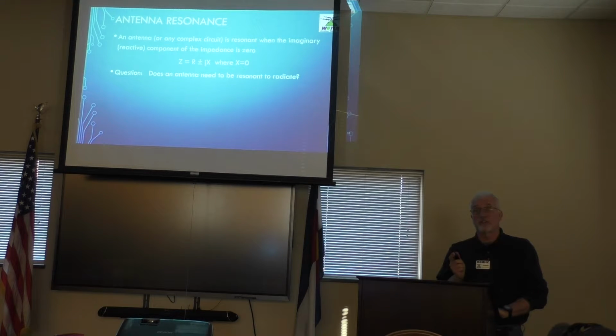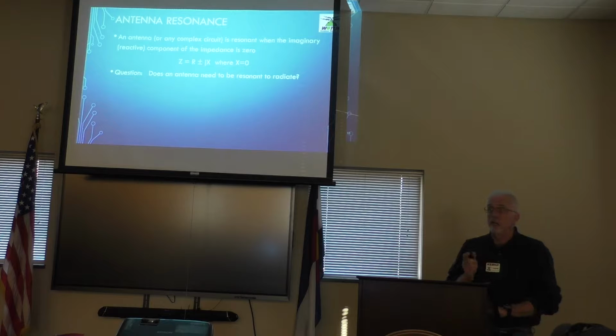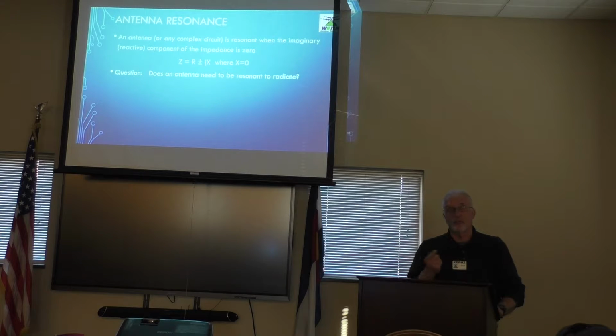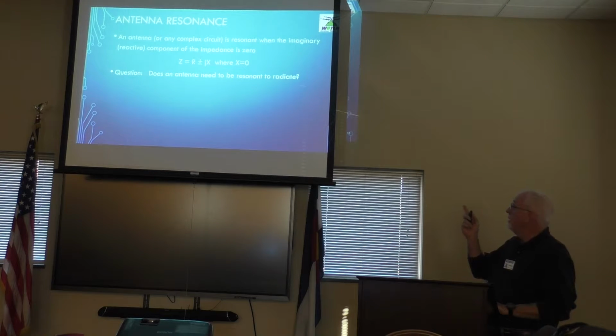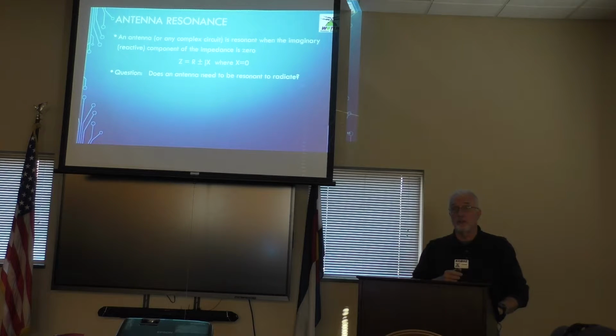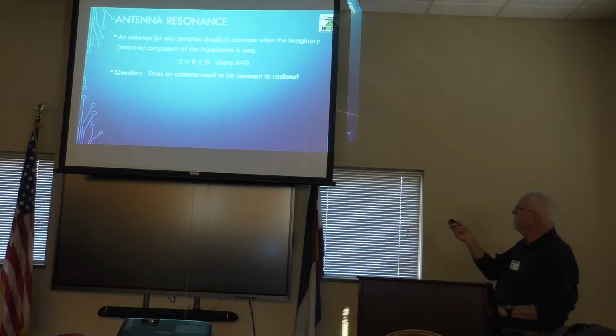Antenna resonance. You hear all the time, and you're going to hear a number of times this afternoon, about a resonant antenna or a non-resonant antenna. Question: does an antenna need to be resonant to radiate? Anybody think that it does? Good, because it doesn't. What it means is that the reactive component in the impedance is 0.